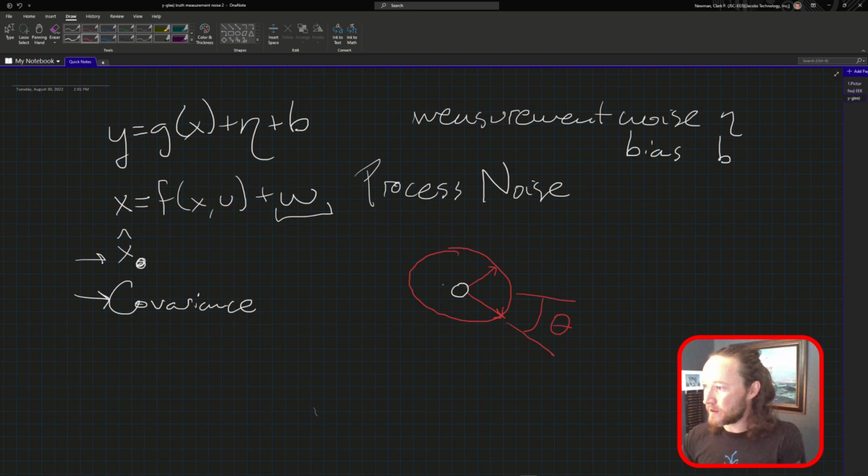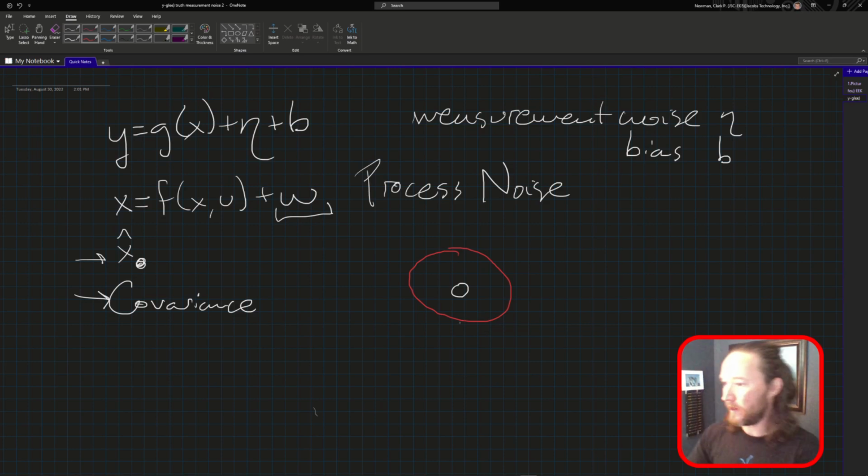What this tells us is that this ellipsoid is defined by a major axis, a minor axis, and a correlation angle, so that you can rotate from our XY plane to our covariance here, which is off at an angle. We have our axes and our correlations, and those give us our uncertainties, otherwise known as sigmas, and our correlations, which tell us how these quantities change together. So we have our spacecraft in its cloud of uncertainty, aka the covariance.